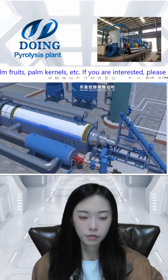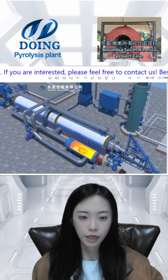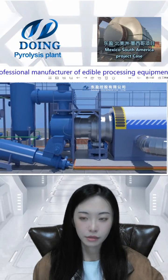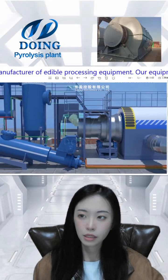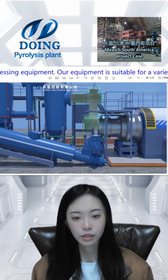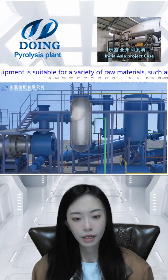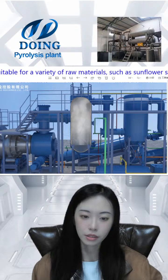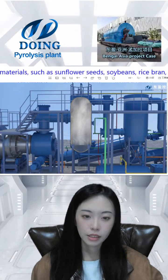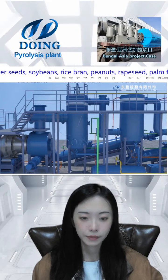The furnace of the reactor adopts this indirect heating design, with flame heating air and an air heating equipment outlet. You can see here the green part of our fixed section, through which the oil gas enters the buffer tank upwards, and the carbon black will fall back to the slagging discharging system at the bottom. And this is a buffer tank. It can be used to slow down the gas and to precipitate the impurities.